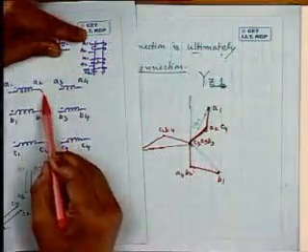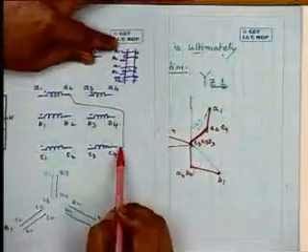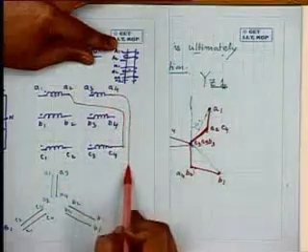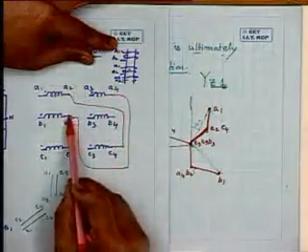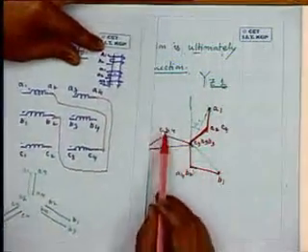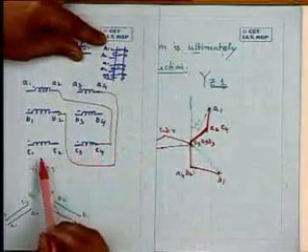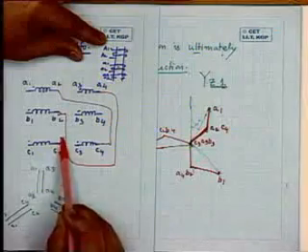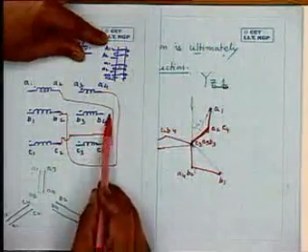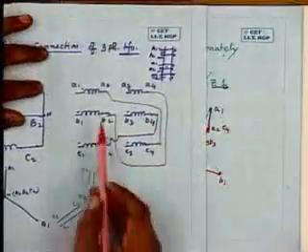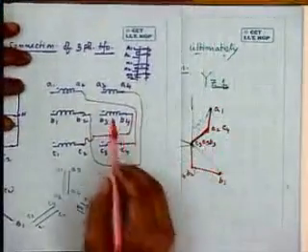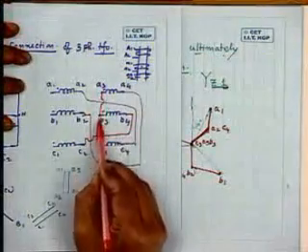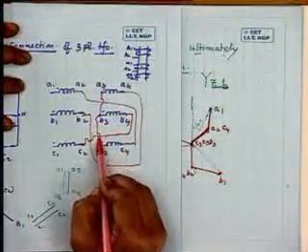So after getting this, I will join it like this. A1 is A1. So A2 should be joined with, say, C4. A2 with C4. A4 with B2. And C2 with B4. Like this I will join. And A3, B3, C3 should be shorted.